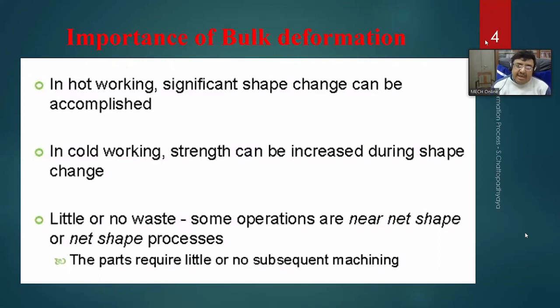Is that concept clear? Yes, sir. You cannot forget this concept. It is easy to understand, but once you understand, you cannot forget it throughout your lifetime. That is called strain hardening. And if you go for hot working, strain hardening never occurs because you are going for recrystallization, and when recrystallization takes place, internal stresses will be eliminated.